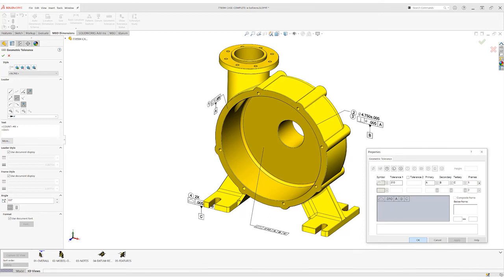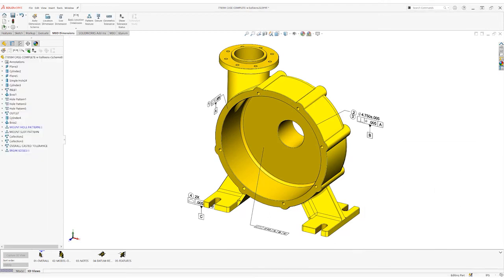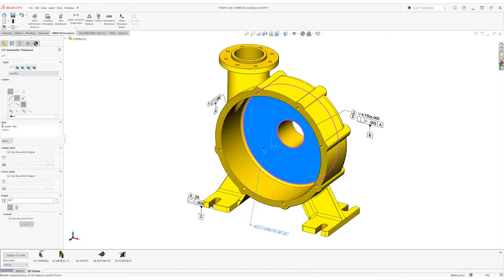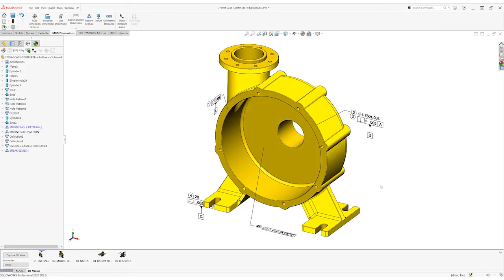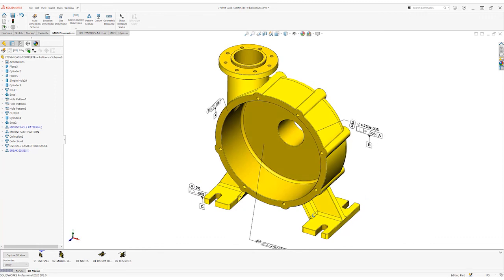Now I want to show you how to create balloon number 29. This is a manual step that requires that you type in the symbology before the tolerance frame. And then that is what told the quality software, the inspection software, which characteristic that is, and we can follow that digital traceability all the way through.